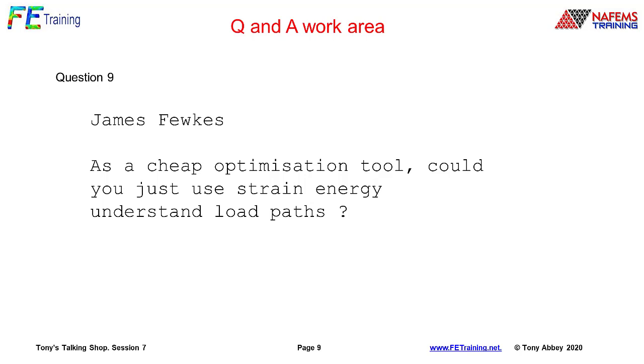James asked a question: as a cheap optimization tool, could you just use strain energy to understand load paths? Yes, you could use strain energy. It would be a great way of doing it. Strain energy density to understand what's happening. And then you can start to say, well, let's remove material here, and that will perhaps give you an idea of what's happening. But as soon as you remove that material, you change the load path, so you've actually got to do a little iteration in there.